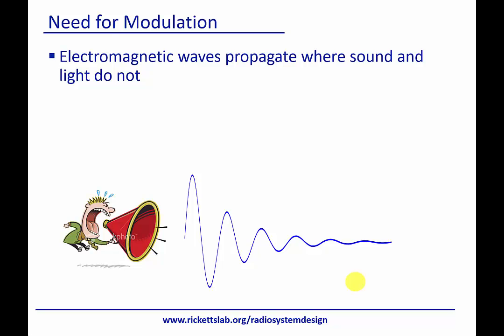So for instance, one of the reasons why people choose 60 gigahertz is because it actually is absorbed by the atmosphere. And you're thinking, well, why would I choose a frequency that gets absorbed? It's actually because if you're putting a bunch of wireless routers in a building, you don't want them all to conflict with one another and talk over one another. So if their range is naturally short, it allows you to make a nice local network.